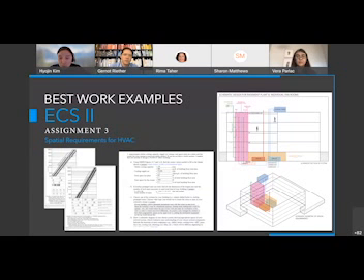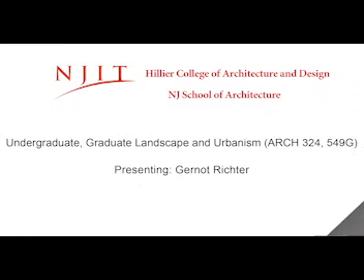And this is the last example assignment I have today. So in this assignment, students are asked to estimate how much space is needed for their HVAC systems and schematically present their locations with labels. So for example, this student found that she needs about 1,000 square feet for the chiller and boiler plant located in the basement of the building, and about 2,000 square feet for fan rooms, which are equally distributed between floors. And of course, the rationale is provided in terms of the program, noise, and control issues.